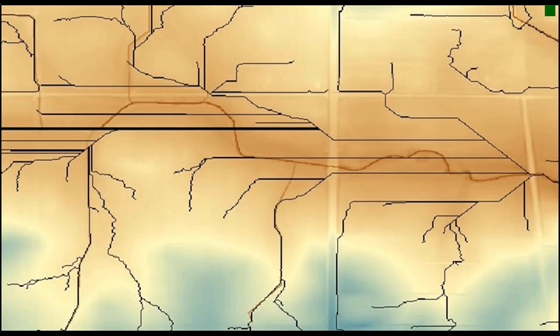If no cut or dam lines are made, there's a good chance your flow paths are going to be inaccurate. Shown below, you can see in the DEM that the flow path should be along that dark brown line, but because no edits were made, the actual flow network that we got, shown in black, is just skating across the landscape, which is not realistic or accurate.